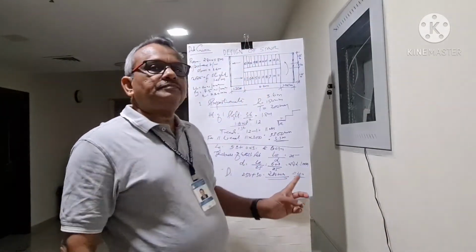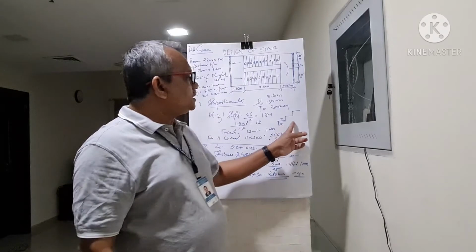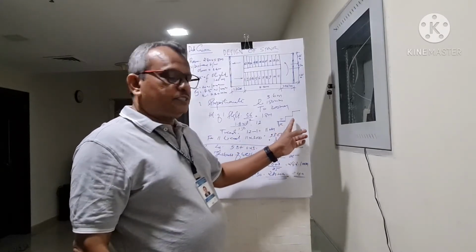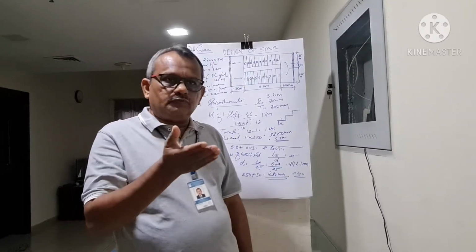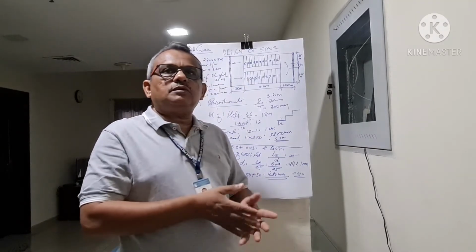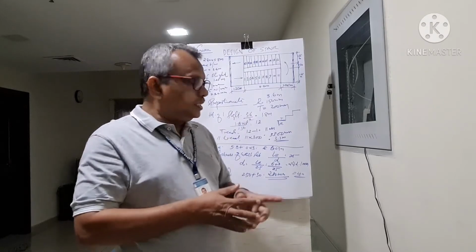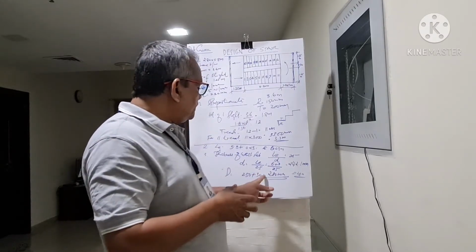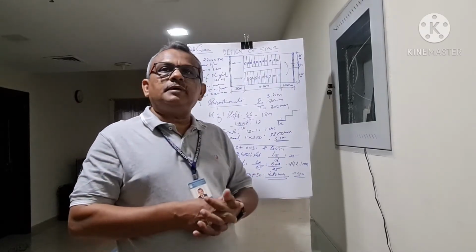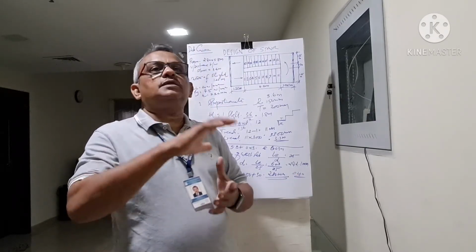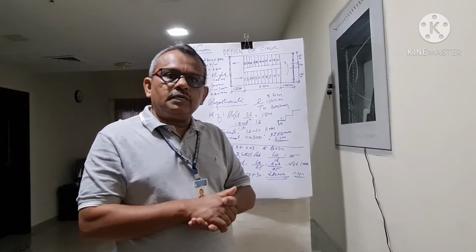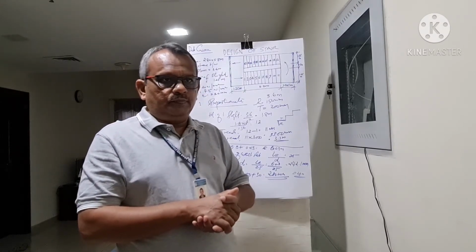So we are taking the value of effective depth of the slab as 242.1, or approximately 250 mm. Once we get the effective depth, we can find out the overall depth. Overall depth of the waist slab here below the steps is equal to 250 plus 30, where 30 is the effective cover from the bottom of the slab to the center of the reinforcement, isn't it? So 250 plus 30 is equal to 280 mm or 0.28 meters, the thickness of the waist slab or the overall depth of the waist slab.